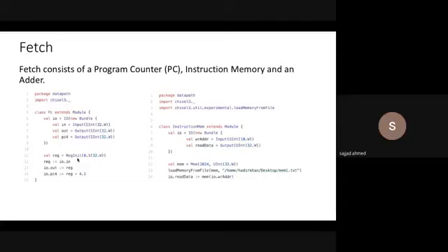This operator between reg and io.in, colon and equals, is a wire operator. We use it in Chisel for wiring something, like wiring an AND gate to its input or output. So we read it as reg wired to io.in. Then we know that we have a word-aligned memory architecture, so we have to update our program counter by 4. Then there is reg plus 4, which increments the register's current value by 4 and sends it back to the input of the register.